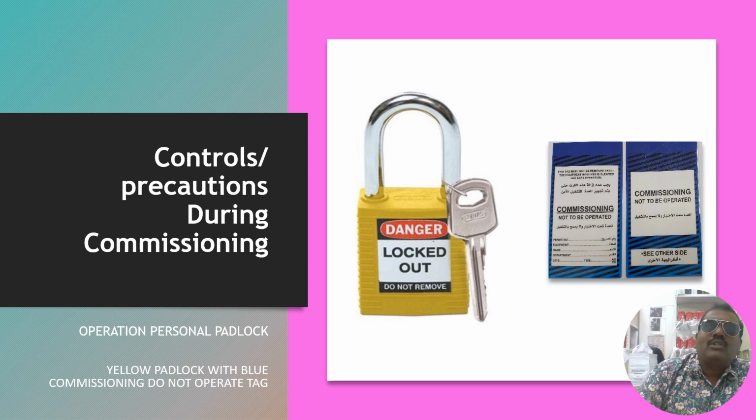Why do the operational departments require this padlock? Because sometimes some of the valves need to be in the open and locked condition, because no person should misoperate the valve, which could lead to a plant trip or plant shutdown. So in this condition they can also use padlocks on site.